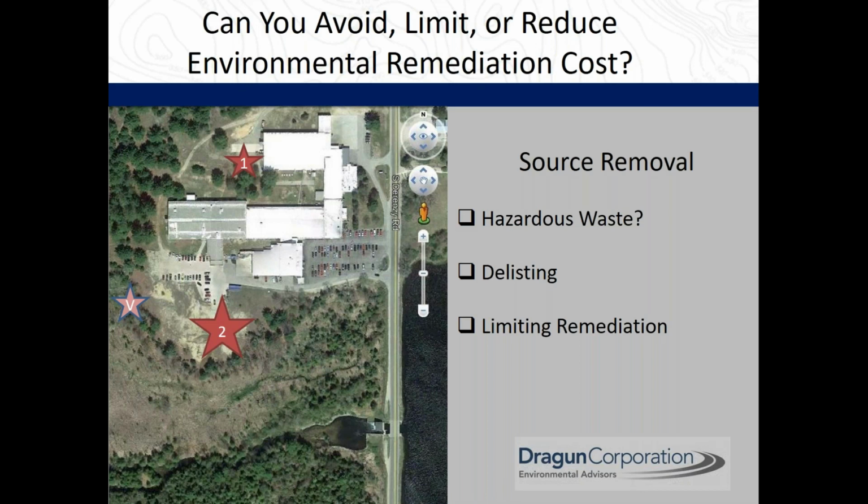And given the site conditions, it made sense to remove the fill material. However, under RCRA, this could be tricky. The main chemicals that were associated with these wastes were cyanide, copper, and some TCE. And from a strict RCRA interpretation, these plating wastes would be listed hazardous waste, in this case from a non-specific source, and mainly under the listing numbers of F006 and F008. And as such, as a listed waste, it would be hazardous regardless of its characteristics. And as such, very expensive to dispose of.